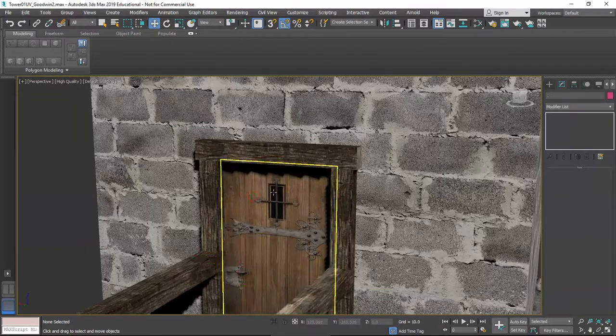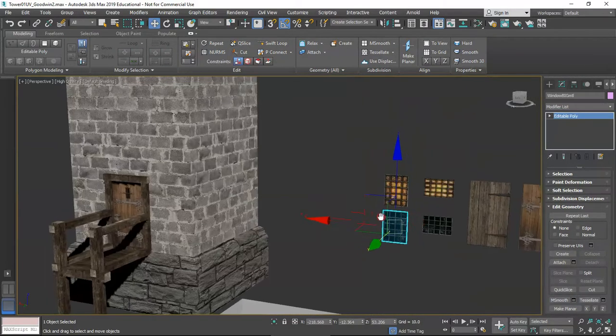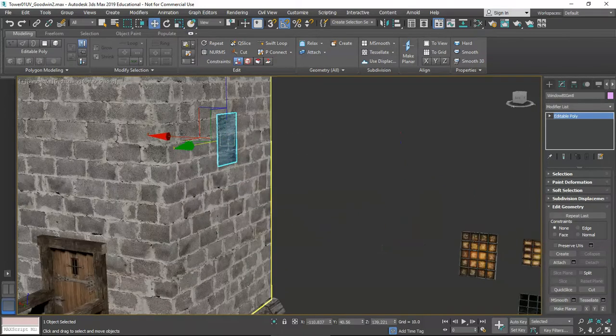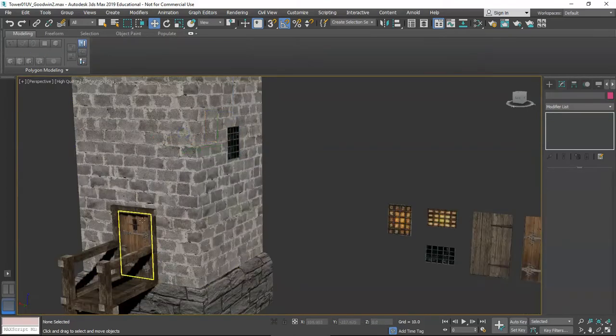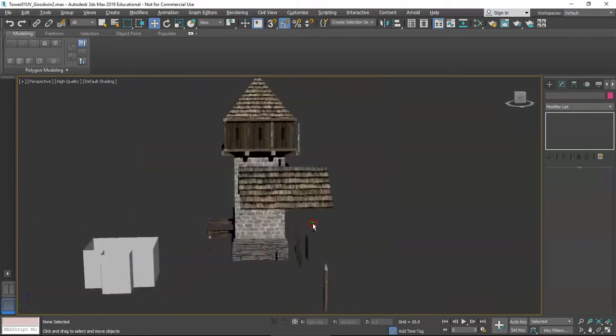And the same way that we did with the door would be the same thing we would do with the window. So if I wanted to add a window, I could just grab the place tool, place it on here, press W, pull it out, duplicate some of the boards and put some boards around it, and we've got a window.